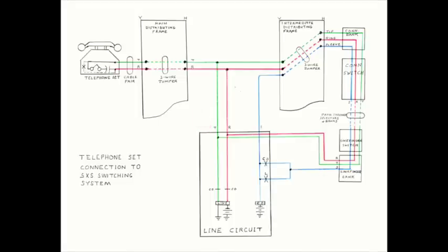The service order identifies the telephone number, so the tech also installs a 3-wire jumper connecting the telephone number on the horizontal side of the intermediate distributing frame to the same line circuit on the vertical side of the intermediate distributing frame. So now the telephone set's tip and ring wires are physically connected to a pair of connector bank terminals. The line circuit has 2 separate sleeve lead outputs.